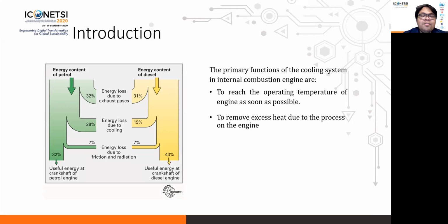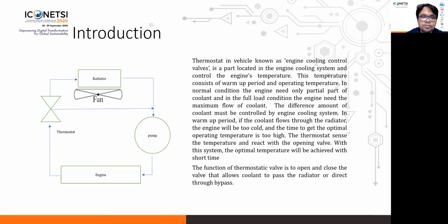The primary function of the cooling system in the automotive engine, the first one, is not to cool down the temperature, but to warm up, to reach the operating temperature as soon as possible. And then after that, it is to remove excess heat due to the process in the engine, I mean, the combustion engine.